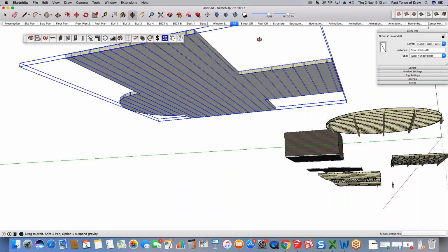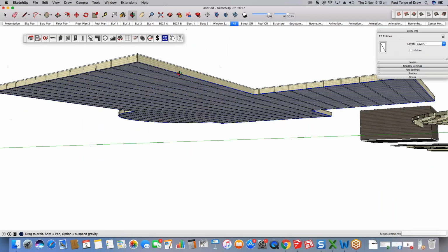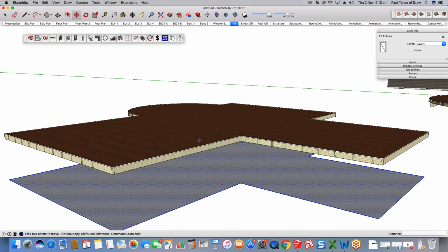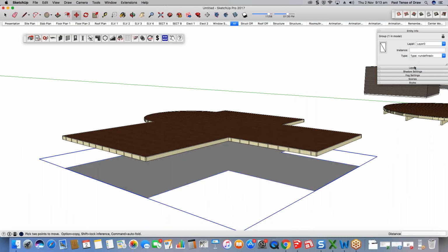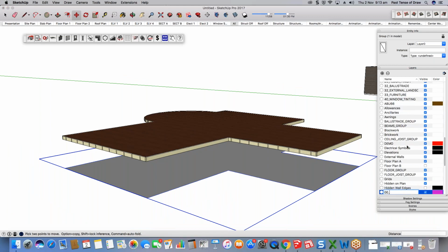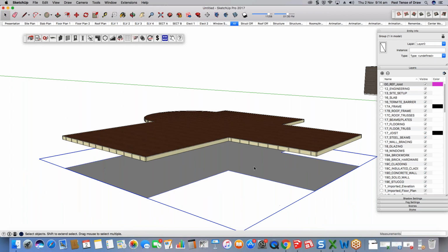As you can see, the shape or the face that you've created, the joist, will remain. So you've got two options. You can either delete them because they're irrelevant after, but if you feel like you might be making adjustments to your model as you go, it can be good practice to turn them into a group and then assign them to a custom layer. So all my custom layers, I pretty much do the 0, 0, so they're at the top of my list of layers. I can find them very easily. And this might just be joist, or maybe it's ref for reference and joist. But you use whatever terminology or naming convention makes sense to you.